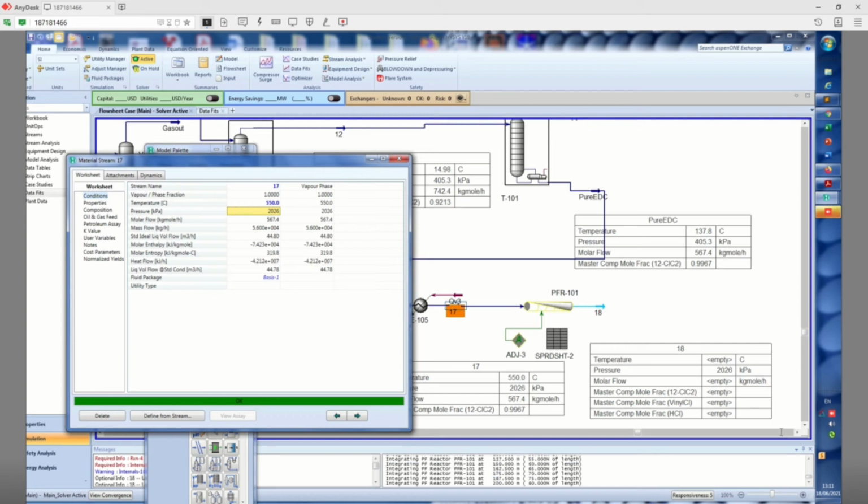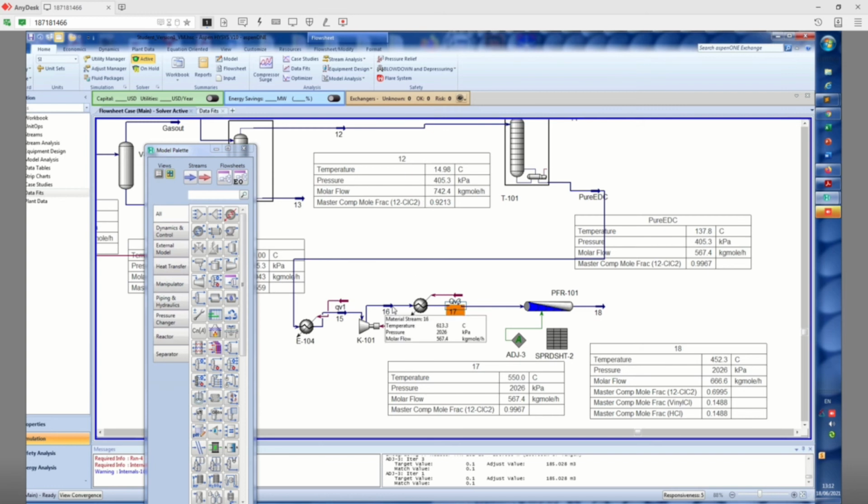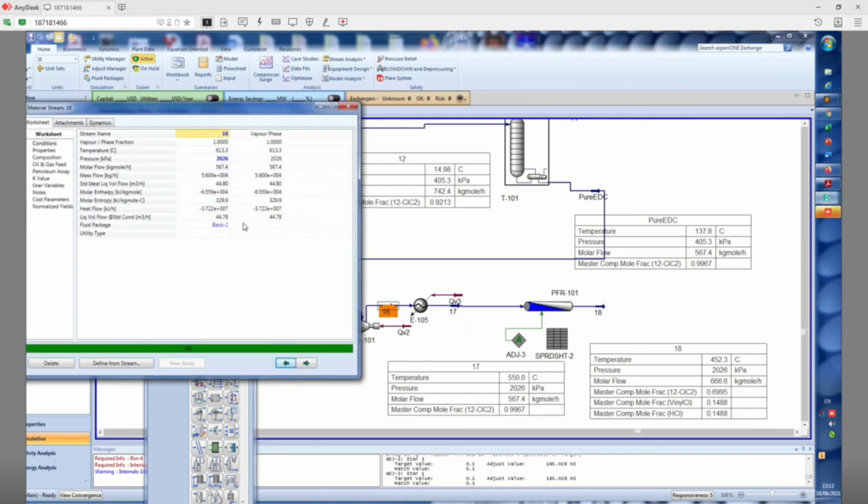And still we are waiting for the calculations for the pyrolysis unit. The results will appear soon in this table. Okay, it's slightly improved. I'm going to increase the pressure to 25 or 26 bar. So close this, so we can change that stream temperature pressure to 26 atmosphere.